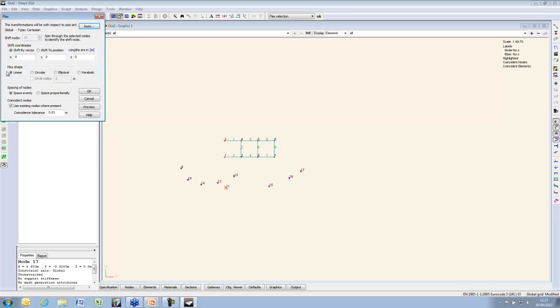And if we have a linear flex, now note that this one is going to be moved by nothing, and the extreme nodes 9 and 17 are going to remain stationary as well, and everything else will be forced to move into a straight line. If we did a proportional move, then it's proportional to their original spacings.